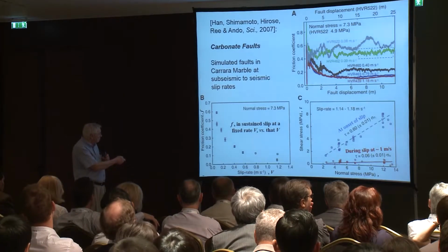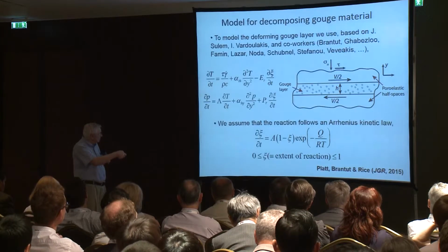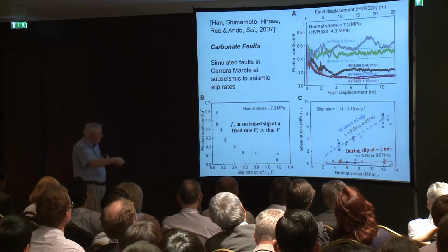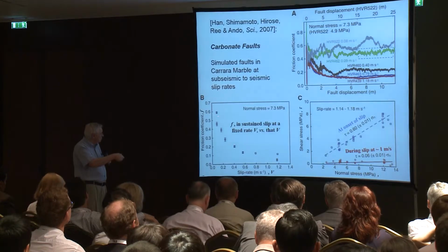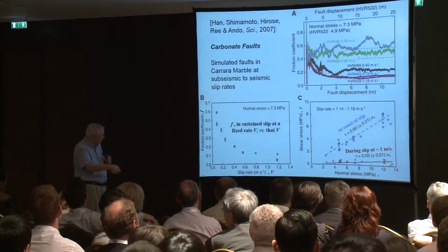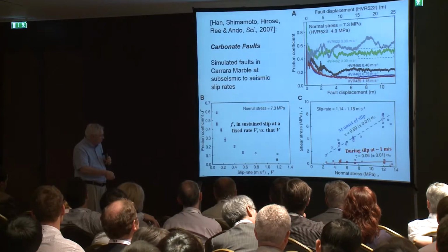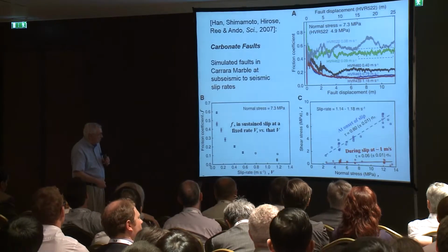And you see the friction coefficient measured diminishes substantially from typical static friction values in the range of 0.6 or so down to extremely low values in the range of 0.1, with increase of the sliding rate that the specimen is forced to sustain.